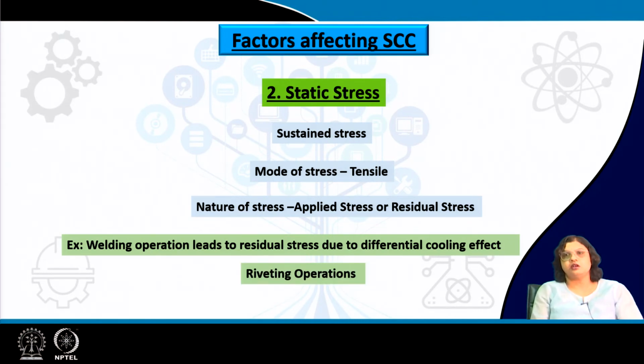The riveting operation is very important, particularly when we are punching the rivet. Sometimes cracks do generate when we are doing this, and punching the rivet also leads to generation of internal stresses. If a crack forms, that is a kind of release of the stresses. Those cracks, particularly under cyclic loading, can lead to fracture.